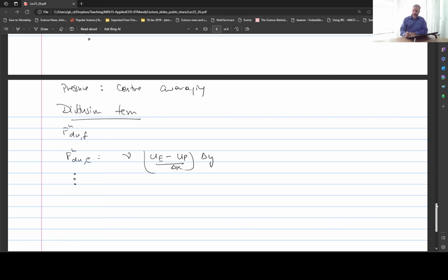So that's typically a finite volume approach. You discretize things on the volume. You integrate the equation over a control volume. Then you use Gauss divergence theorem to convert those volume integrals to surface integrals. So you have integrals over the surface, and you need quantities over the surface, not inside the volume anymore. It's a very, very useful theorem.